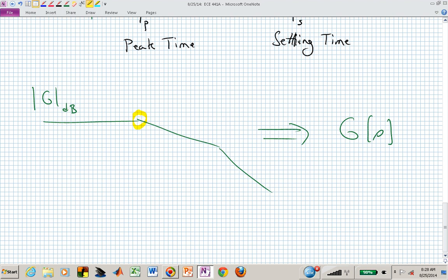that location. And if the frequency axis is provided on that plot, let's say as a function of omega, then you can identify where that particular pole is located in the frequency, for its frequency. And then you would have another pole or break out here. And if your system is minimum phase, then all you need is this magnitude plot to identify g of s.